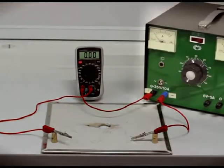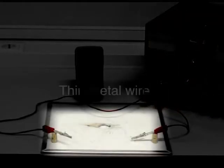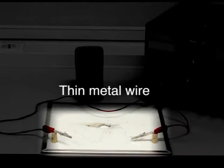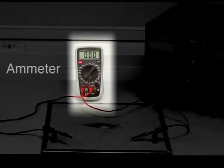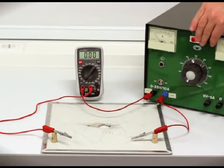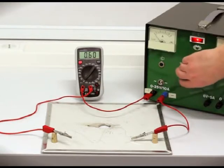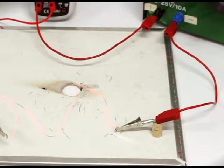Heating effect of an electric current. Let's start with an experiment. We have a power supply, that's a DC power supply, a thin metal wire, and an ammeter to measure current flow. We switch on the power supply and increase the current flow. Observe that at near 1.9 amperes, the thin wire becomes red hot.